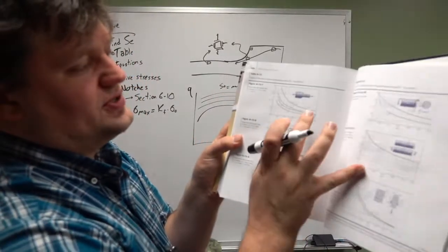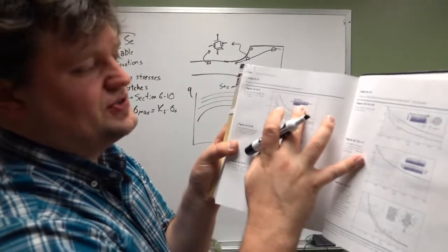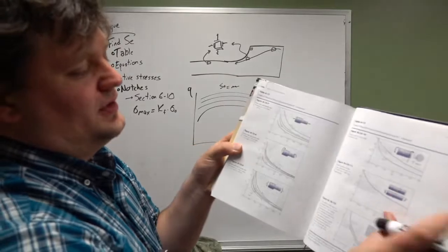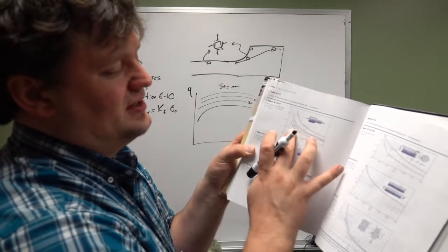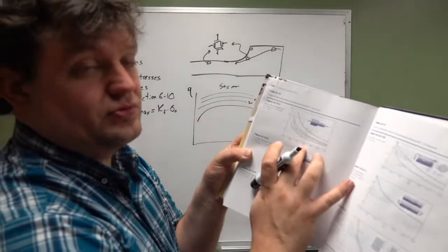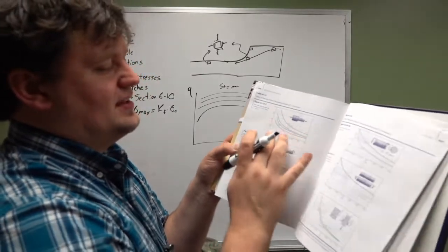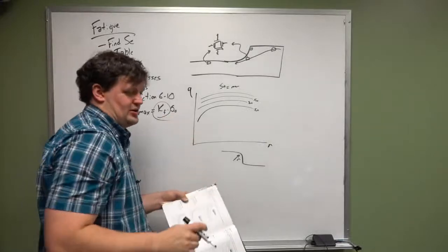Here, what it shows you is, let's say you've got a round shaft with two different diameters, and it has some fillet with radius r. The ratio of bigger diameter to little diameter, as that changes based on the radius of the curve to the little diameter, is given based on that K_t value, which is ultimately used right here.